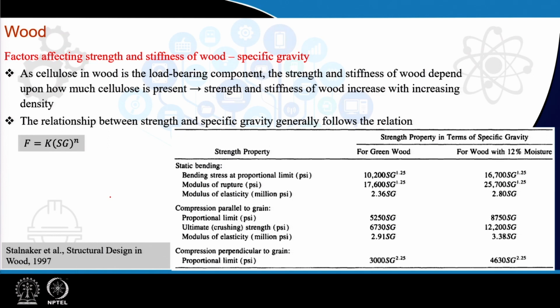So, as the amount of pores increases, both the strength and the density decrease. So, basically it is not the strength as such, the important thing is the specific property, which is sigma over rho. If sigma over rho can be maximized, then the pores can be beneficial in giving better specific properties.